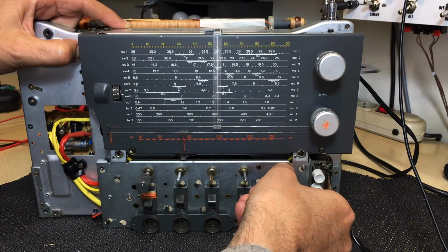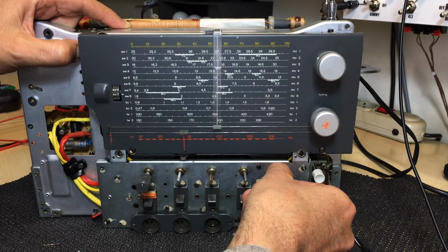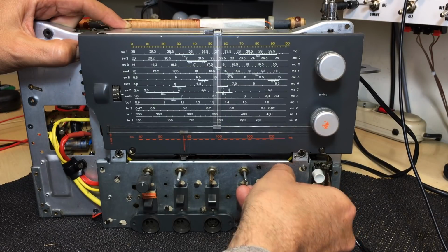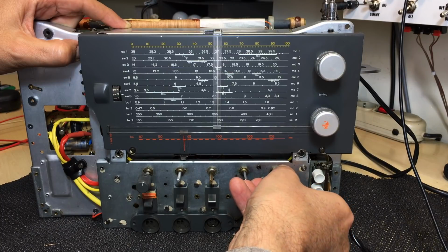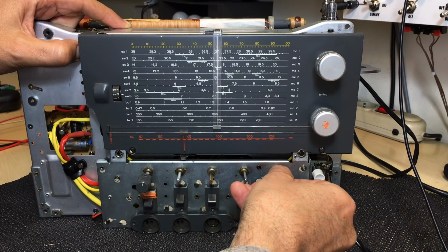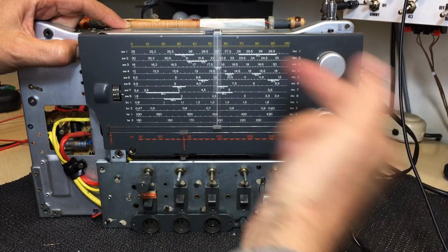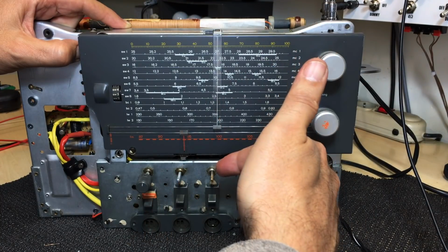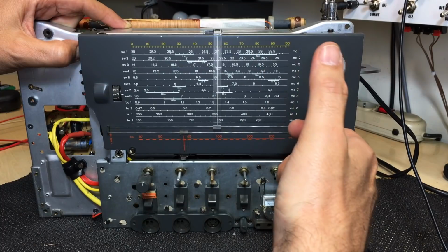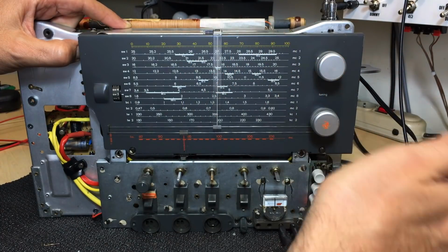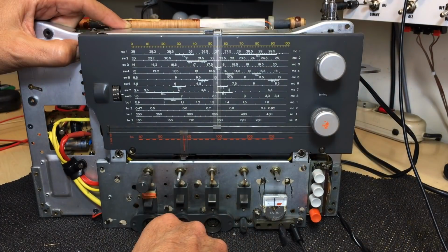Now if I tune it exactly, you see I'm tuned away, I'm tuned in line. All this radio is doing is this station is feeding a signal which has a carrier at 455, which is the IF that's produced, and it's meeting the BFO. So it's doing exactly the same thing as I was doing when I fed that carrier in there.